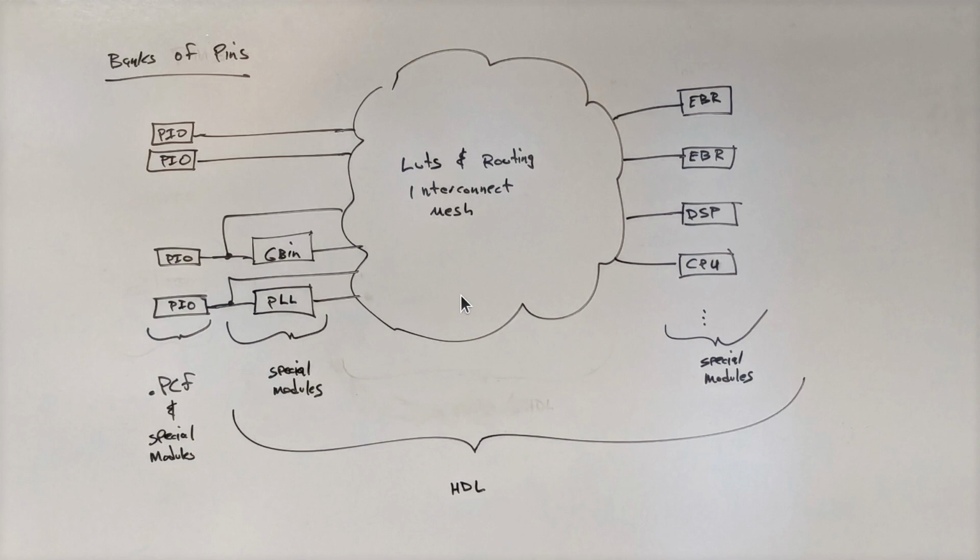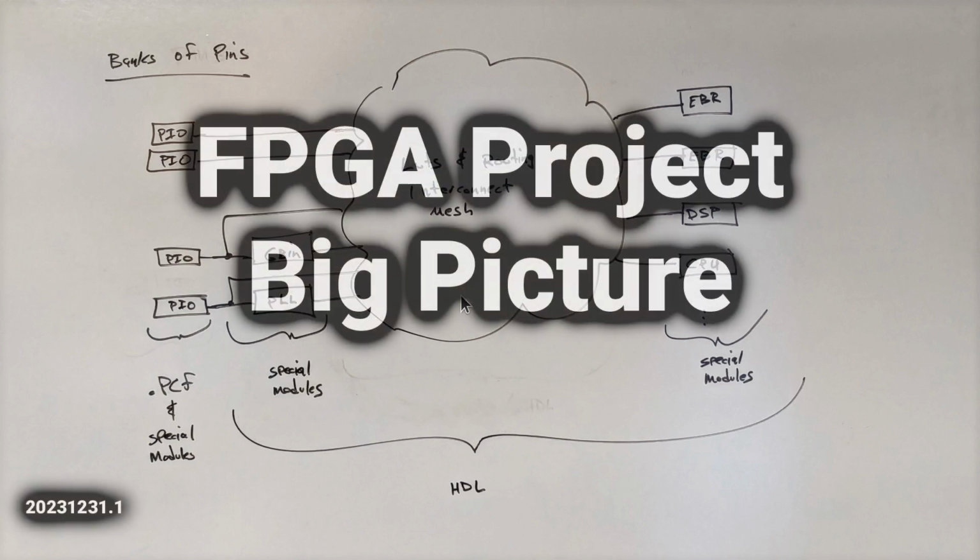And that will require us to focus a little bit more on the test bench code and how to organize our projects so that there's always a way to add a test bench to one of the modules so we can check them independent of other things in our design. Because you can't design the whole thing and expect it to work. We're going to have to test these individual modules incrementally as we go. And that'll be a skill we're going to have to build up in order to be proficient at this whole thing.